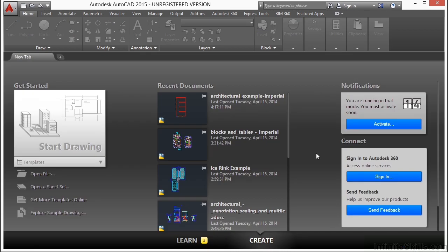Most of the time, your drawing won't have a layer in it that you need or want to use. It's just something that happens. To eliminate this issue, I recommend that you start every new drawing with a template file that has your most common layers already put into it. Regardless of how you started your file, though, you're going to need to make a new layer. I'm going to show you how.